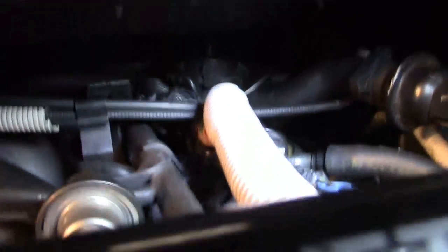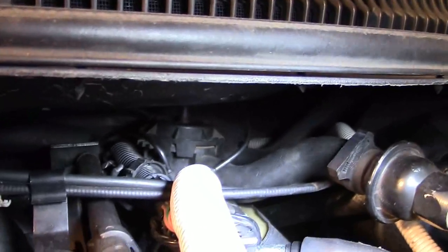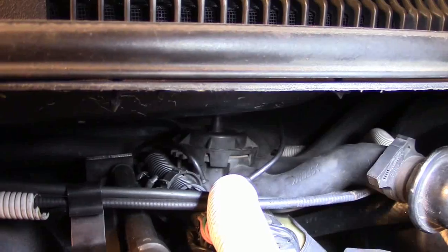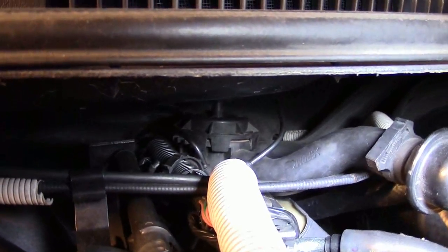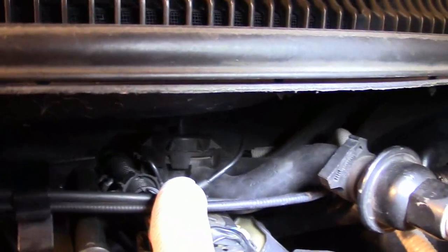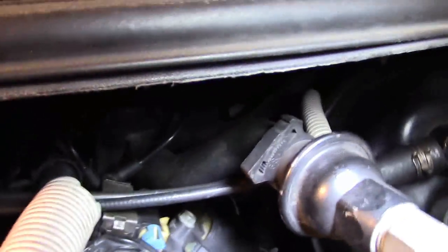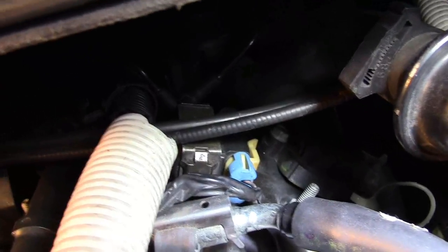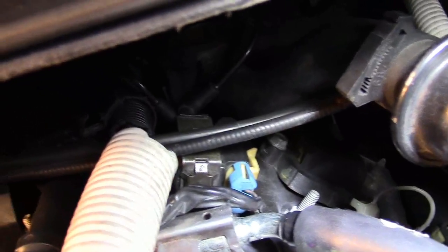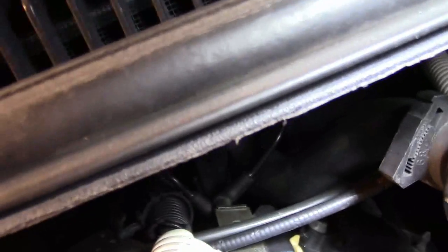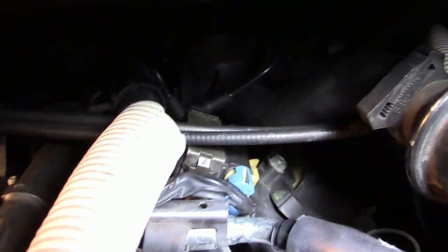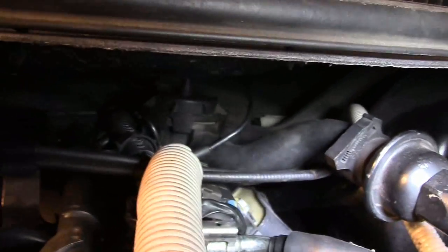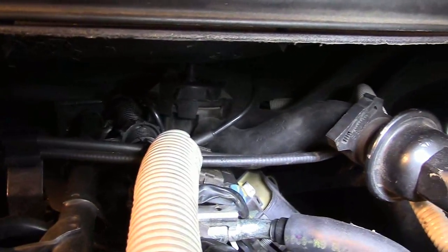We can also see on our UFO looking thing there, which is obviously the control or diverter valve, there is a vacuum hose on top of it. I'll bet that vacuum hose goes to a solenoid. If we follow that vacuum hose, we can see with the blue electrical connector and the yellow clip there, that is clearly a solenoid. There are two hoses connected to the solenoid there, two vacuum hoses. One, of course, to the valve, and the other one is, of course, going to go to vacuum.